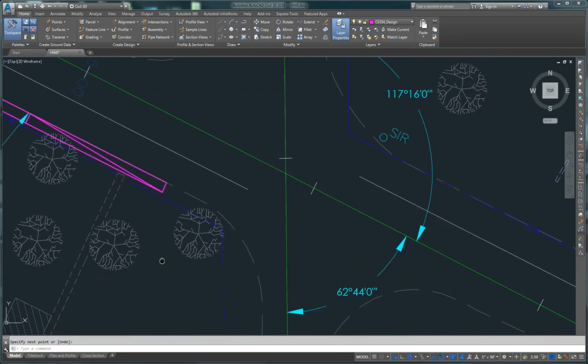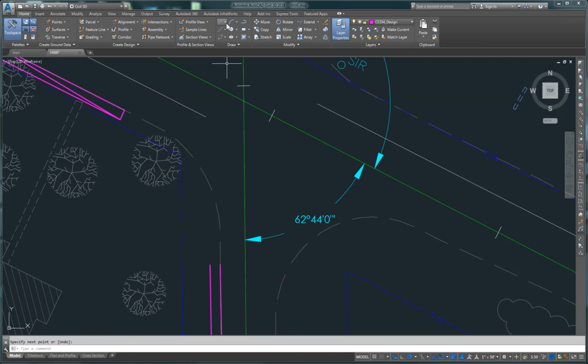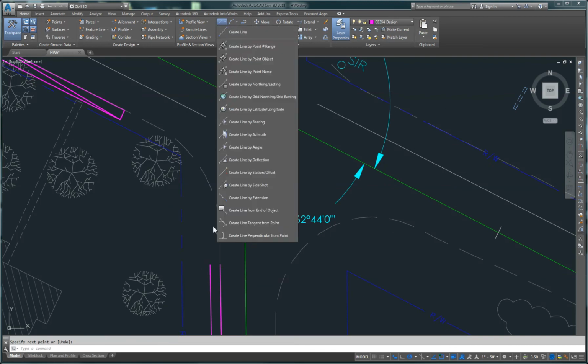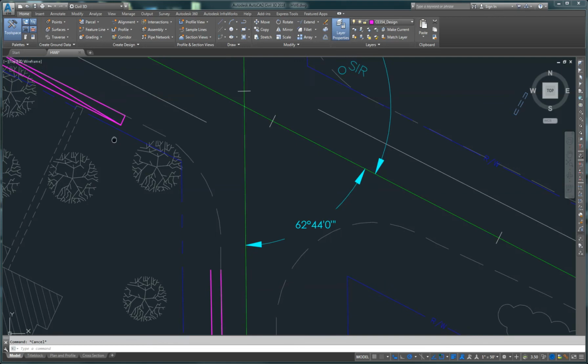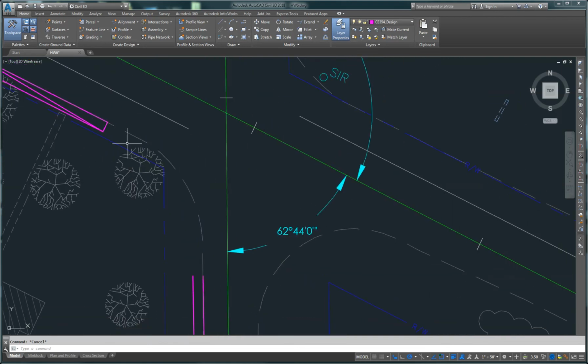And actually first, we're going to do the same thing over here. Actually, we're going to wait. So that just shows you how to draw in that taper rate. Now let's put the radius in. And so you've got a radius listed in the chart as well. And we're going to use the fillet command for that.